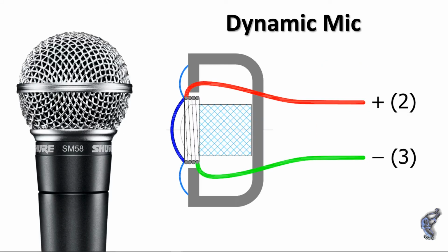Dynamic mics are the most common type. Their construction comprises a dome-shaped piece of mylar suspended above a magnet assembly. A very long piece of copper wire is wound in a circle, edge to edge, and glued to the back of that mylar diaphragm. When assembled, that coil of wire rests in a magnetic air gap.